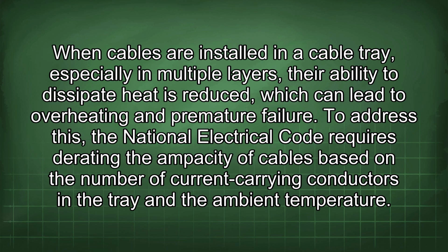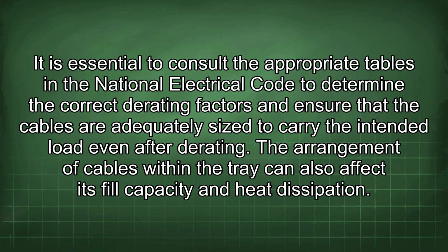To address this, the National Electrical Code requires derating the ampacity of cables based on the number of current-carrying conductors in the tray and the ambient temperature. It is essential to consult the appropriate tables in the National Electrical Code to determine the correct derating factors and ensure that the cables are adequately sized to carry the intended load even after derating.